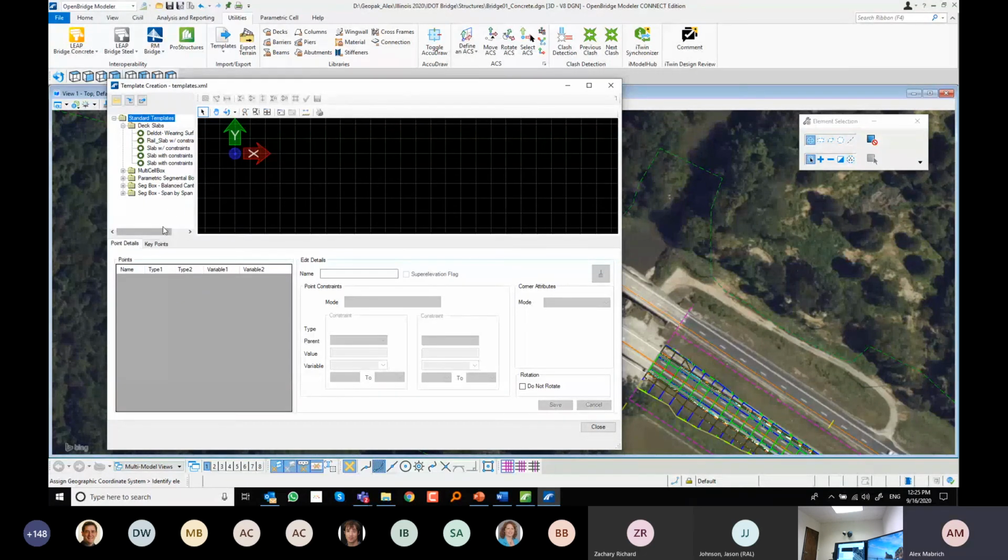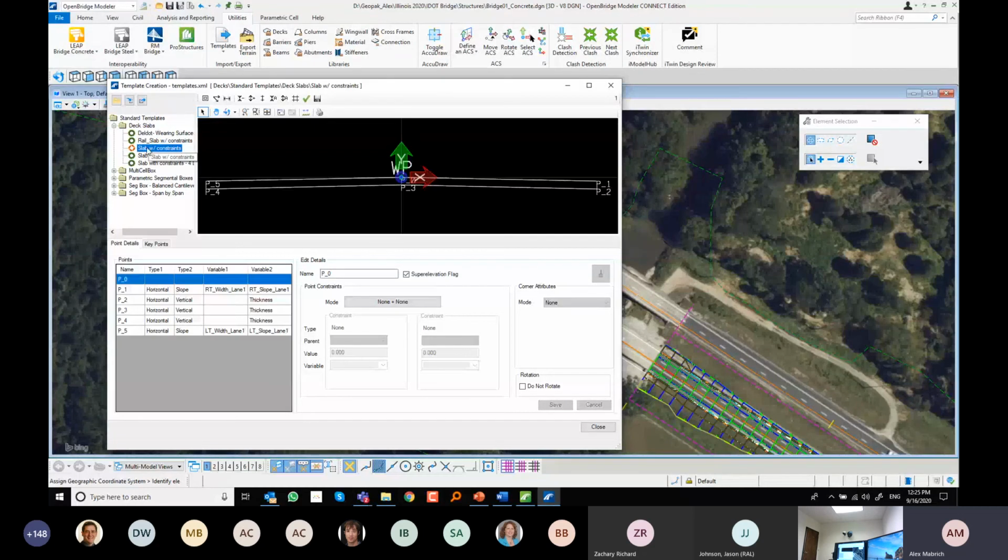And then you just generate it and say, well, this is my deck. And that's what I'm going to use. Right now, this deck is variable because we put it into variables. So right out of the box it is 20 feet and 20 feet, so it's a 40 feet deck. But if I need 60, I just change the number and the deck just widens.